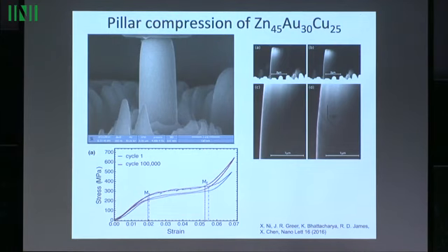This is transforming. It's about 6 or 7% strain, and this is 300 megapascals. I guess it's going up to 600, 700 megapascals. If you're not familiar with those units, that's a lot of stress. For example, in this building, the steel that holds up this building, or even a taller building, the yield stress of this steel, in other words, the failure stress of this steel, would be somewhere around here. So at each cycle of 100,000 cycles, it's getting a lot of stress, and it's reversible. So that's quite unusual behavior, both in the hysteresis and the reversibility.